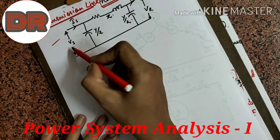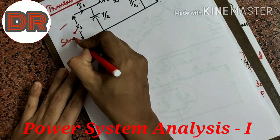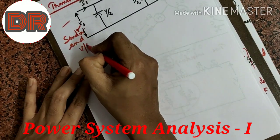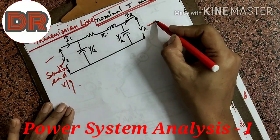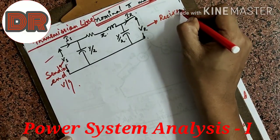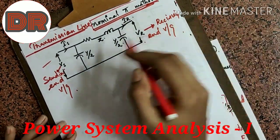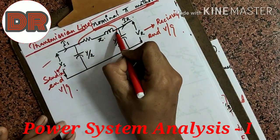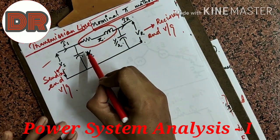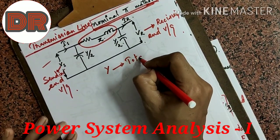We have Vs on one end, that is the sending end voltage, and we also have Vr on the other side, that is the receiving end voltage, and in between we have a series impedance. And we have Y as the total shunt admittance.